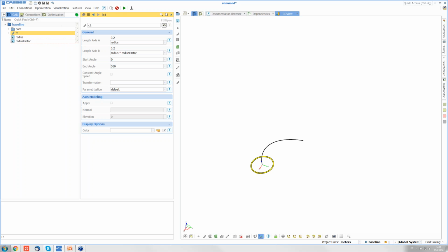All right, and let's just name this curve section. And now we have specified our cross section. The parameterization we have done to the cross section is that we can change the size of the two axes of this ellipse. And now another thing that we would like to do is that, of course, rather than having the cross section fixed here at the start of the curve, we would like to be able to sweep it along this path that we have defined.